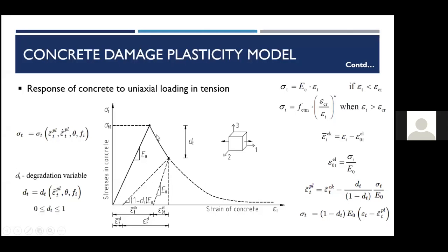Normally, this induces strain localization in the concrete structure. We normally say concrete is brittle, but concrete in tension is not actually treated as an elastic brittle body. You have to take into account phenomena such as aggregate interlock, and when it is reinforced concrete, the rebar effects like bond slip, dowel action, etc. To take these phenomena into account, the decrease in stress in the concrete in the tension zone should not occur suddenly, but gradually. Then the aggregate interlock and the interaction between the reinforcement and concrete can be considered if you consider this portion. This is sometimes called tension stiffening. So even cracked concrete can take some tension.